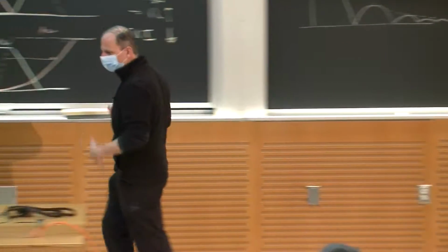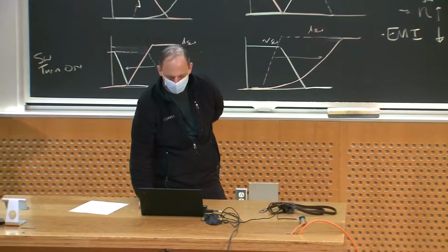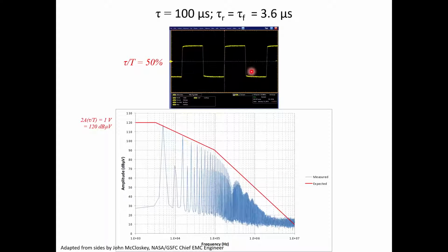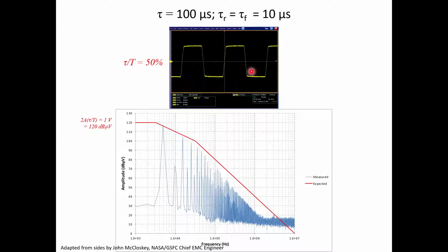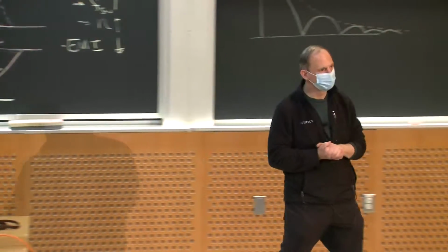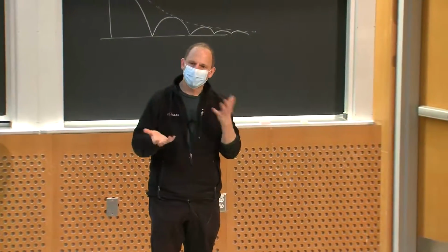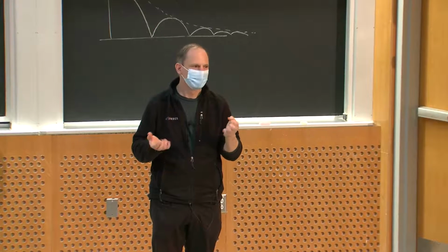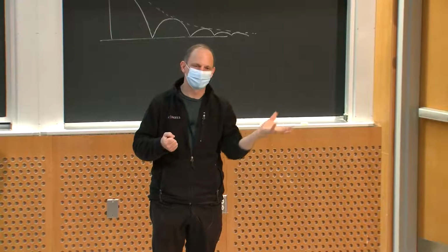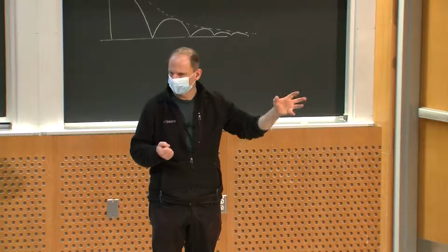So one of the effects you get, as you slow down the slew rates, is that you start to kill off a bunch of high frequency content, okay? Now, your filter is typically sized for the lowest frequencies, right? But when you put parasitics in there, remember that we saw the circuit parasitics make the filter start to drop out its capabilities at high frequency.